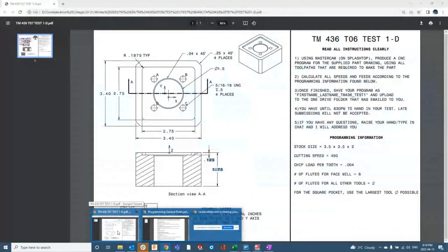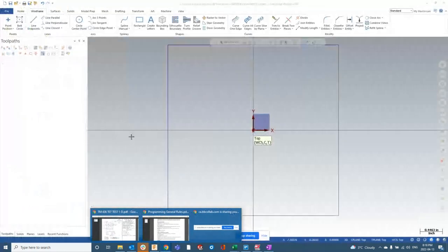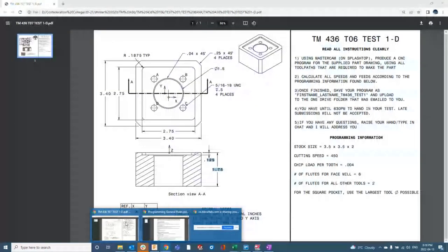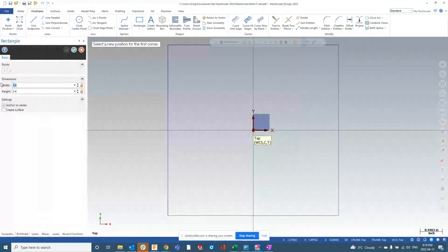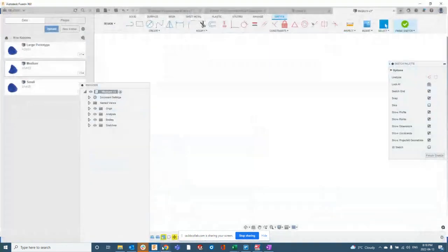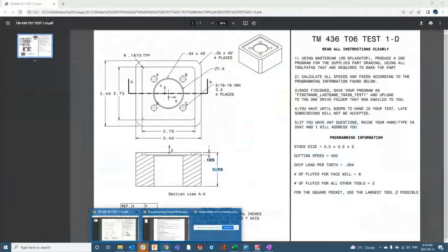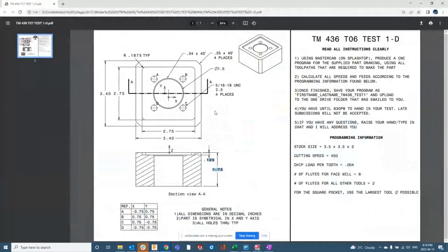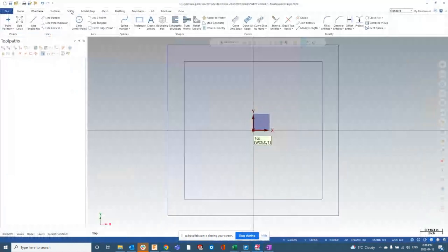And then it's going to be an inside square, 2.75 by 2.75. Okay, so same thing, another square, 2 points. I should make my center first. 2.75, tab, 2.75, enter. Okay, then we have a circle. Oh, my bad. Circle that's diameter 1.5 inches.